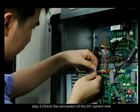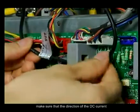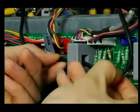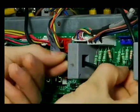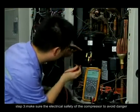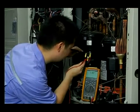Step 2. Check the connection of the DC current wire. Make sure that the direction of the DC current is the same as the arrow marked on the inductor. Step 3. Make sure of the electric safety of the compressor to avoid danger.